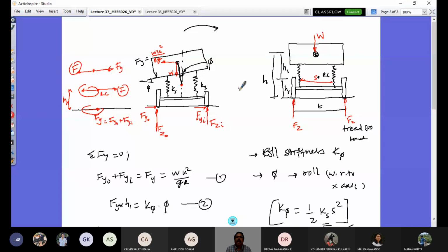of the derivation. Also, let us look at additional design aspects like camber and lateral load compliant steer effect. What do I mean by that? There are some more effects. We will see all that. The roll that happens in the vehicle would also induce a roll steer, something we have discussed. So what would be its effect? There is some understeer influence. There are influencing factors of the understeer gradient, which we have looked at, and we will see them in the forthcoming classes. And then we will do rollover stability analysis, and that completes the fifth module.